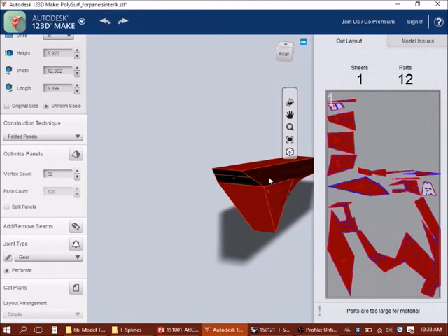I say here a hybrid structural system, meaning that some of the opaque walls, or thick solid walls, may end up being load-bearing walls, and some of the framing pieces, the rest of the skeletal system, may sort of lean on that, and that would then be a hybrid system, as opposed to it all being load-bearing or all being a frame. So that's what I mean by that hybrid system. So you might share a little bit of both.